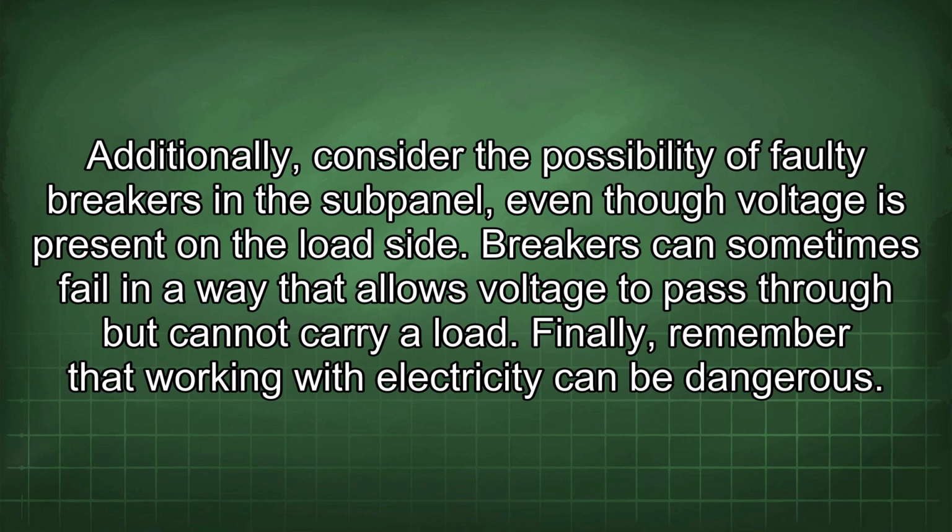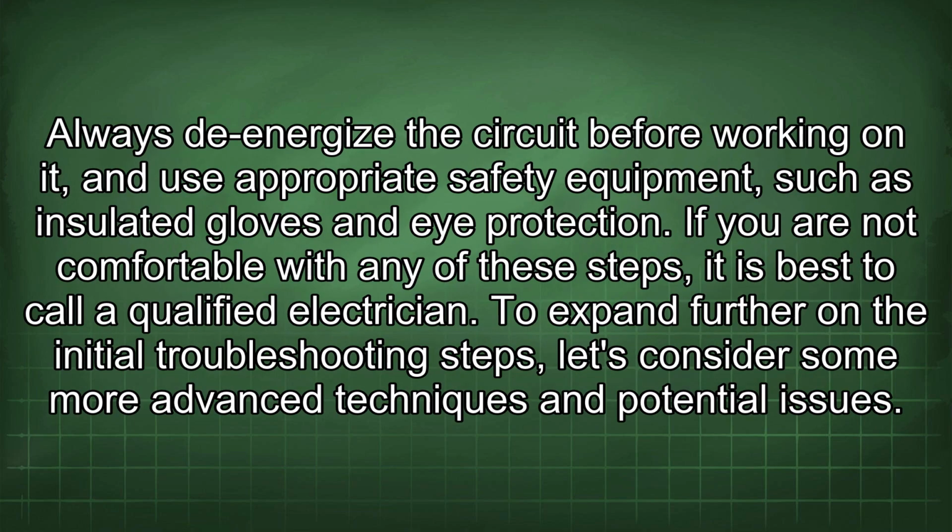Finally, remember that working with electricity can be dangerous. Always de-energize the circuit before working on it, and use appropriate safety equipment such as insulated gloves and eye protection. If you are not comfortable with any of these steps, it is best to call a qualified electrician.